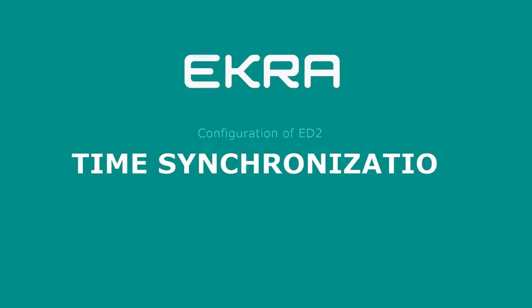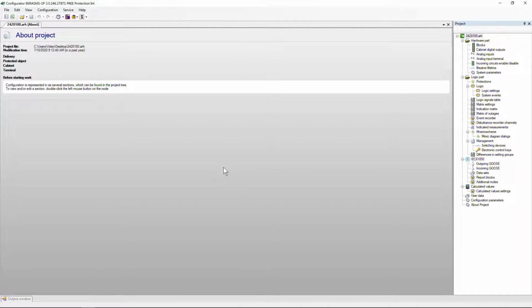In this video tutorial, you will learn how to set up time synchronization of an ED2 series IED. Next, we will consider setting in the Configurator software. Similar settings can be made in the Smart Monitor software. Before starting to work with the configuration, it is recommended that you watch the video tutorial on configuring of ED2 IEDs, opening and saving of configuration file.